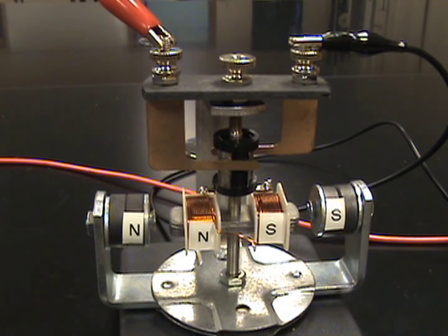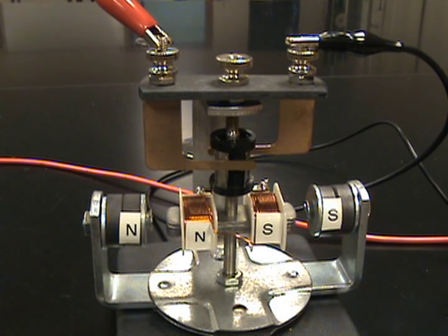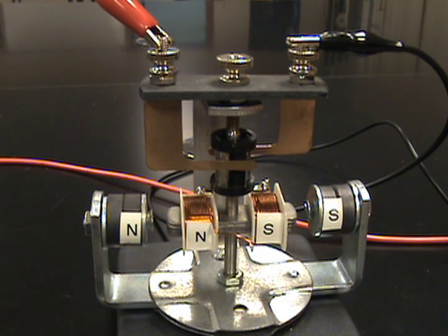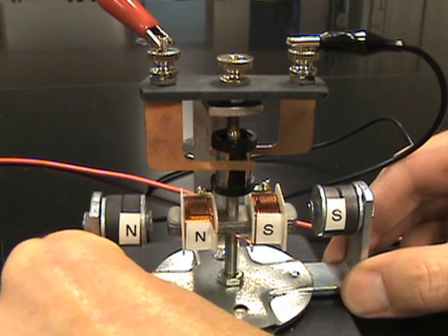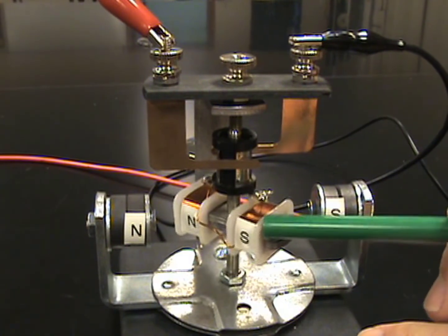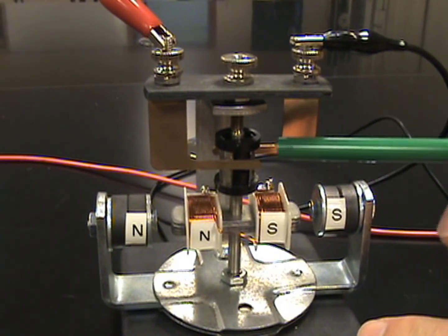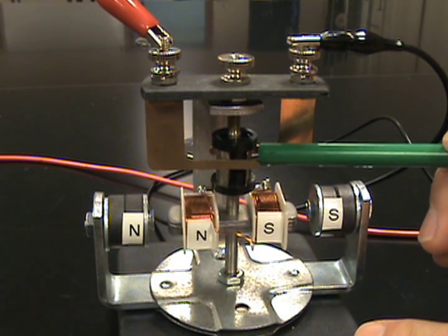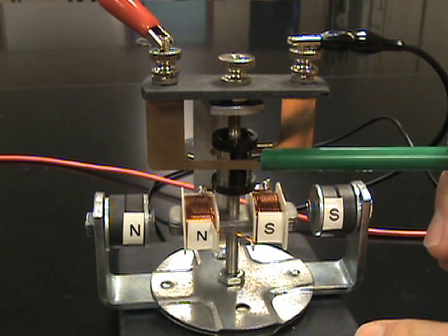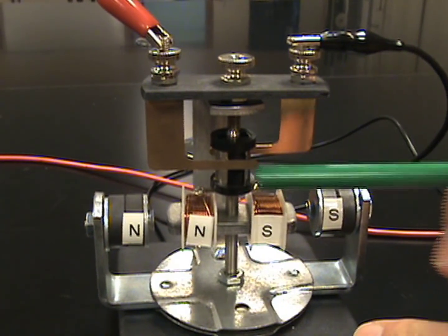So here, folks, we have an electric motor, which is a device used to convert electrical energy into mechanical energy. Now, there are many different types of motors. This is a St. Louis motor, but all motors have certain features in common. You'll notice here with this motor we have two permanent magnets which are surrounding an electromagnet which is attached to this armature so that it can spin freely. Also notice up here we have a metallic brush and a second metallic brush here which make contact with a split ring commutator here, and you'll see that split in the ring right here.